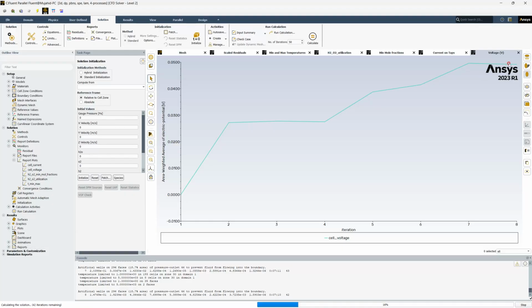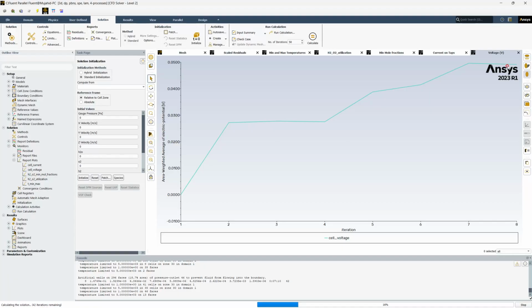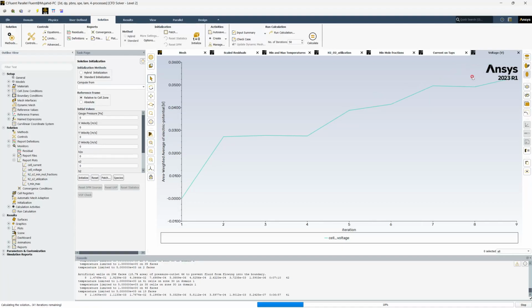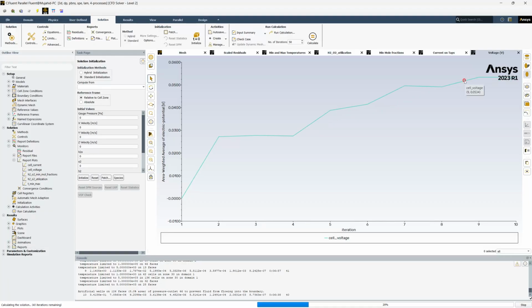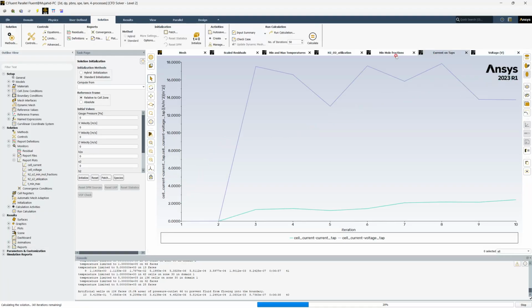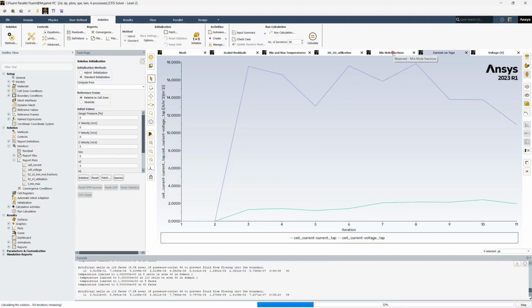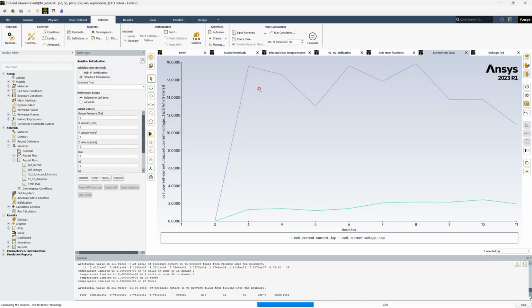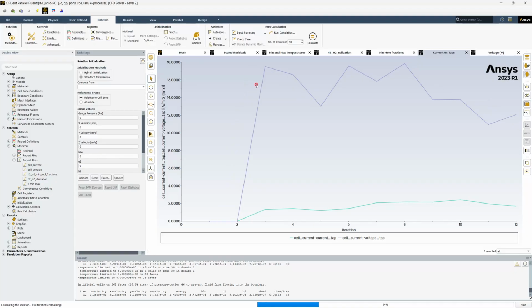So, actually the voltage should increase because I've got a very small value for the current, so the voltage should go as near as OCP. That should be around 1.1 to 1.2 volts. So let's let it complete the 50 iterations, and then because the solution will have converged quite a bit, it will have good values in all the nodes. Then we can decrease and increase the relaxation factor for momentum and for the current also.